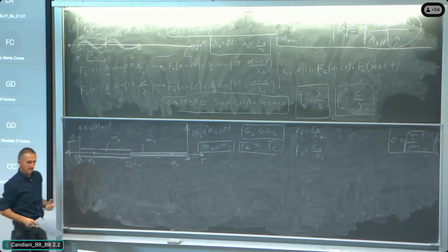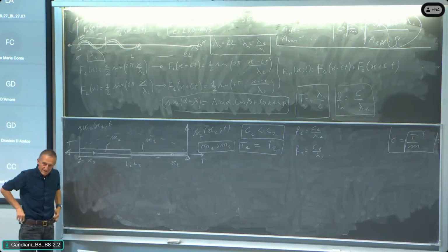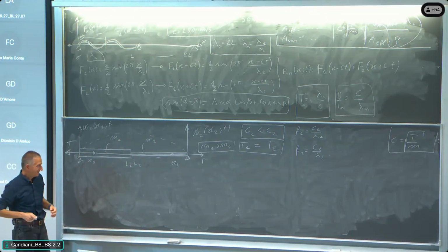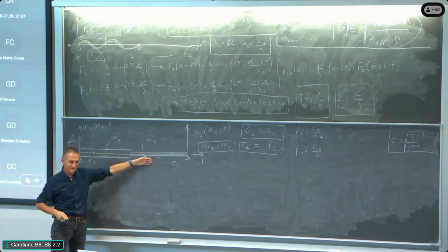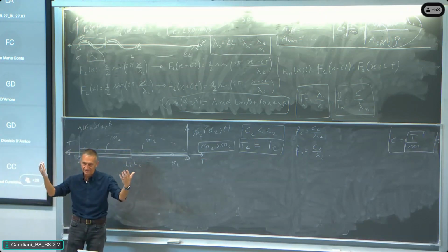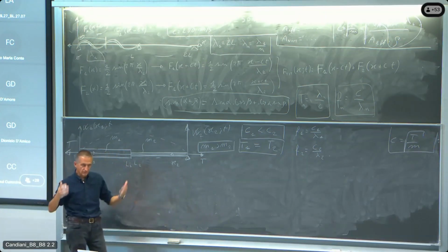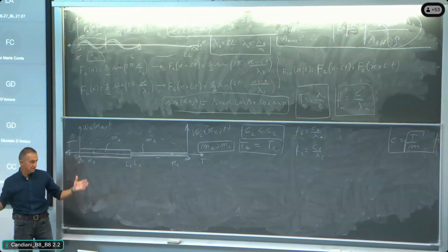In this different shape, there is one first thing that we must be aware of. The frequency is the same on the left and on the right because we have one mode of vibration. The structure is made by pieces having different characteristics, but the frequency of the overall mode of vibration of the structure is exactly the same.